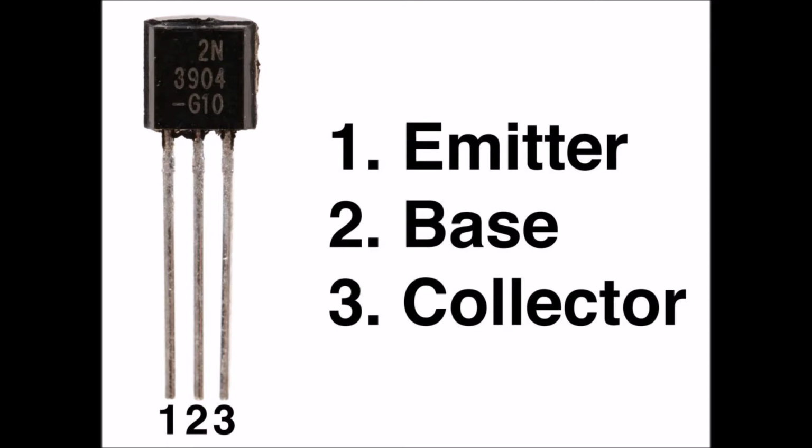When we want a bipolar transistor to amplify a signal, we must bias the device so that a small change in the current between the emitter and the base will result in a large change in the current between the emitter and the collector. The ideal voltages for EB, the base bias, and EC, the power supply voltage, depend on the internal construction of the transistor and also on the chemical composition of the semiconductor materials that make up its N-type and P-type sections.